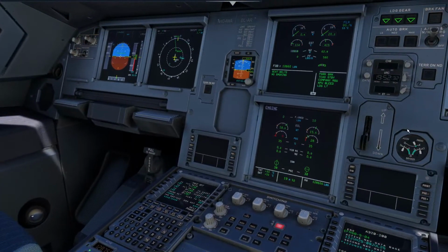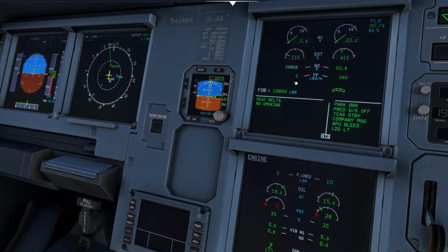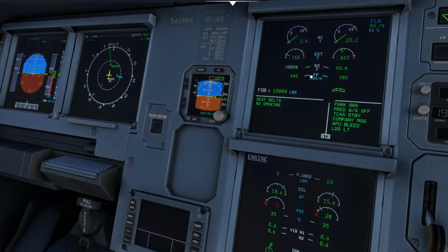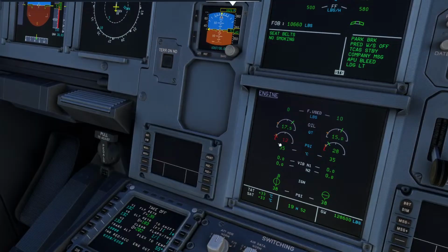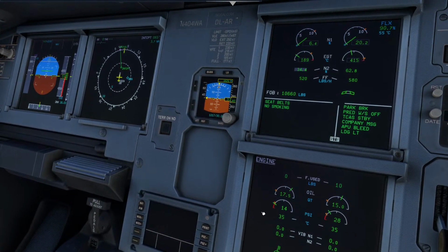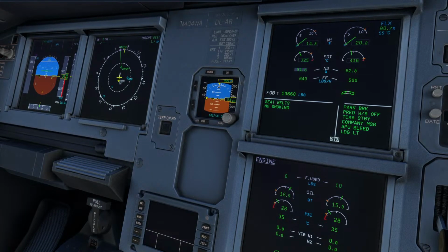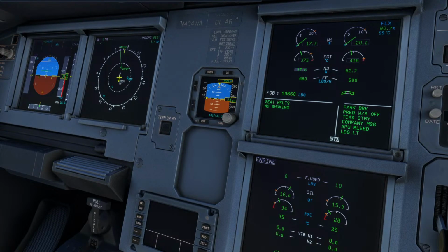And same thing. There's N2. No oil pressure yet. We do have some N1. There's fuel flow, so it automatically introduces the fuel. There's EGT, N1. Oil pressure's coming up still. And I said it's like taking candy from a baby. Look at that, that's pretty impressive, man. Dude, they put so much work into this airplane. It is amazing. And so, you hear that clicking sound? No, because I muted it. Oh, okay, never mind.